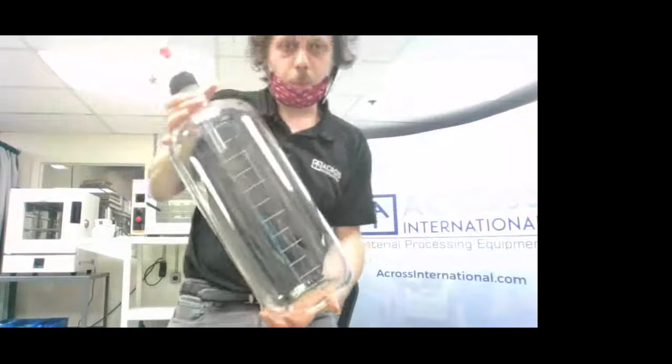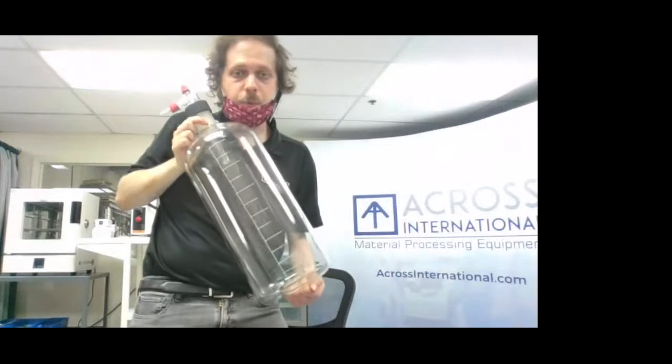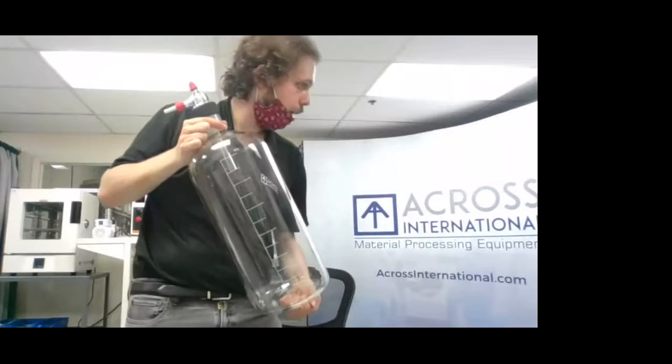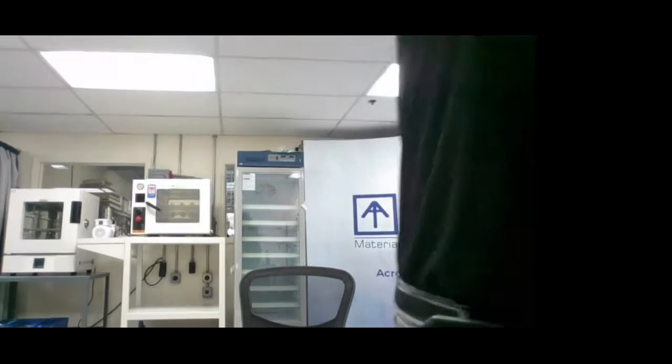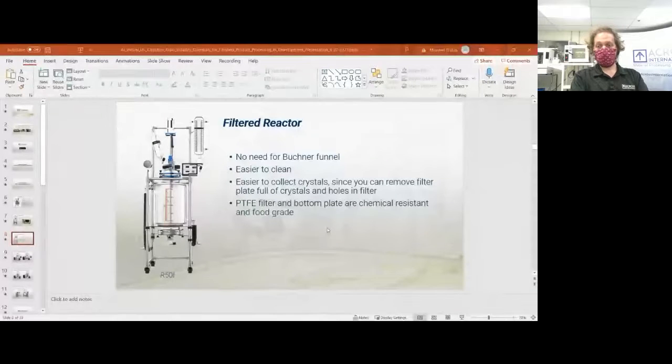You can use a vacuum carboy like this and essentially pull vacuum on an intermediary area between your reactor drain and your filter, so that you can pull any liquids through while filtering through a filter paper. I don't recommend doing very fine filtrations in the reactor unless there isn't very much particulate. Typically, you would do only pretty coarse filtrations in the reactor because you don't want to put positive pressure on our glass reactors. Our stainless steel reactors can go under a mild positive pressure.